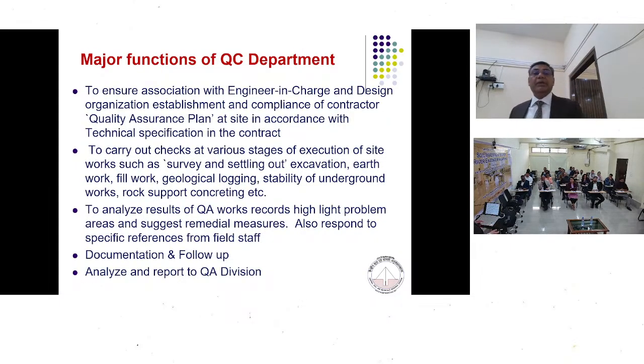Major functions of the QC department: to ensure association with the engineer in charge and design organization, establishment and compliance of the contractor quality assurance plan at site in accordance with the technical specifications of the contract, to check the various stages of execution of site work such as survey and setting out, excavation, earthwork, fill work, geological logging, stability of underground works, rock support, concreting, etc. So the QA team has to be involved in every aspect, whatever is going on.